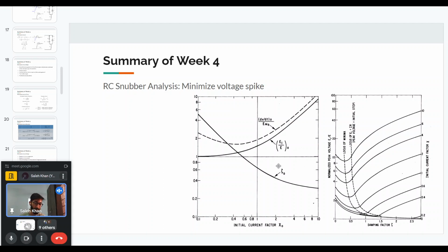It cannot be in the millihenry range, for example. The parasitic inductance will not be in the millihenry range for a well-designed converter, and it cannot be as small as a few picohenries. So usually it is in the hundreds of picohenries to some tens of nanohenries, this range.